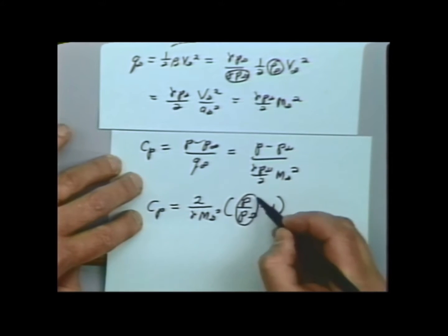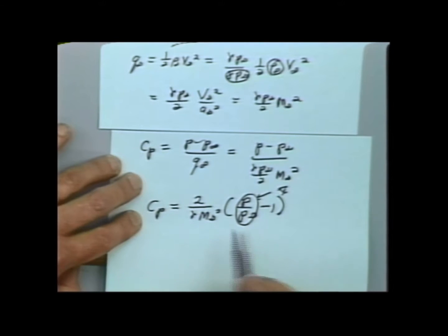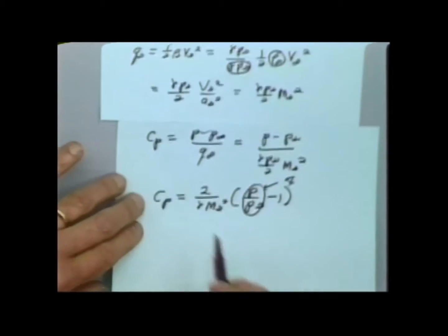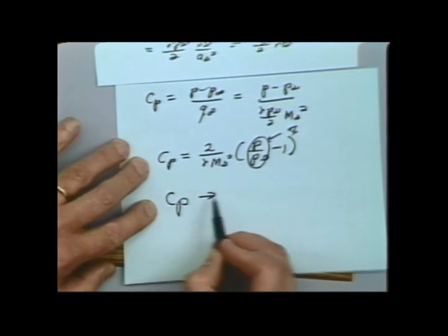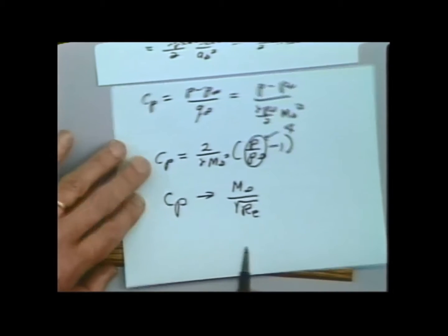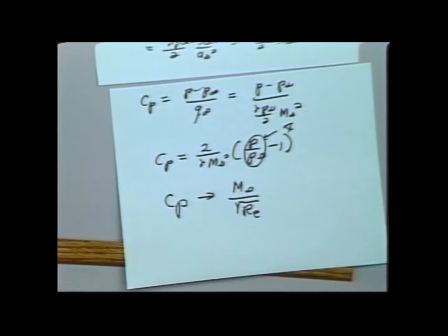This is the thing that's correlated by chi-bar. But now we're dividing it by an M infinity squared. Conclusion: the pressure coefficient should be correlated more by something like M infinity to the first power over the square root of the Reynolds number, and that is indeed the case.